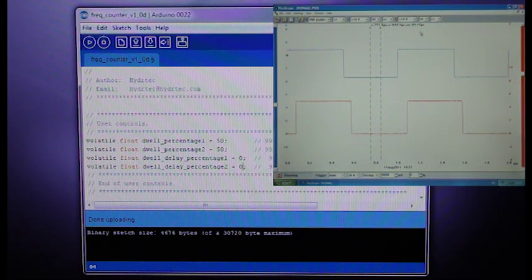I'll just remove these cursors for now. Delete. Where's the delete key? There it is. Delete that one and delete that one. And what we'll do is increase the frequency of the input pulses, or the input pulse stream, to see how stable the output pulses are as the frequency increases. Remember that at the moment it was set to roughly about 1 kilohertz, 1 pulse per millisecond.